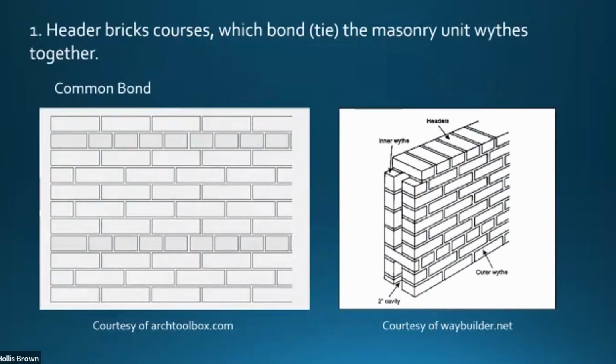When you have brick basement walls that are 3 brick thick, laid in Flemish bond, I can only speak for myself, but I've been doing this for 30 years and I've done about 18,000 home inspections and I've never seen a brick foundation fail unless someone was monkeying around with it. They either did digging behind it or cut a door through it. They did something that affected it, but on its own, you really can't beat a solid brick wall that's all interlocked like that. They almost never fail.